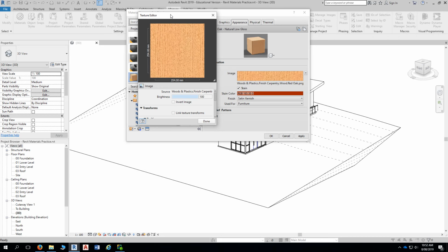The other important aspect of texture maps in getting the material looking correct when it maps is the scale. Quite often students will create a material but forget completely about the scale. If you're producing a material based on a standard brick, it's important that you get the scale correct, so that when it maps to your brick wall surface, it looks correct.